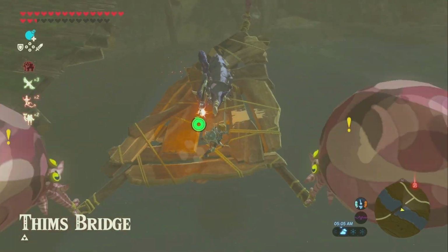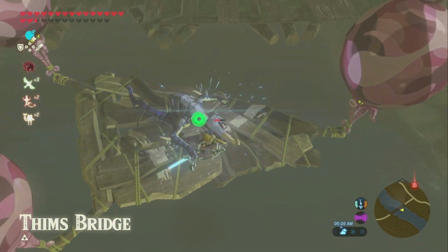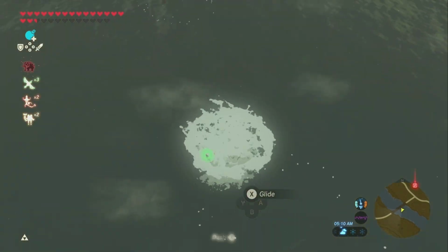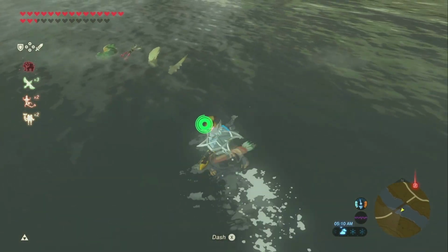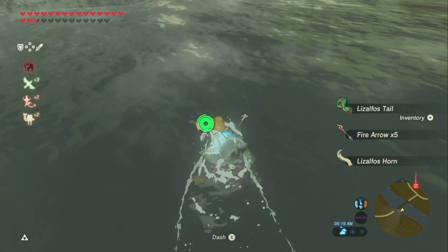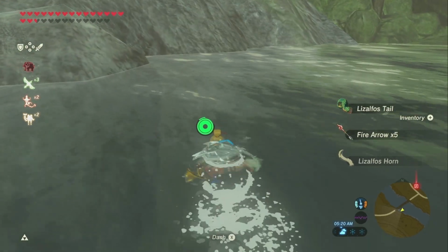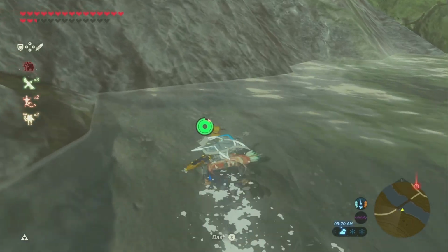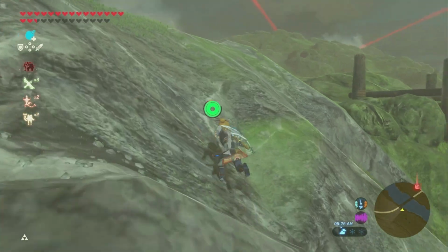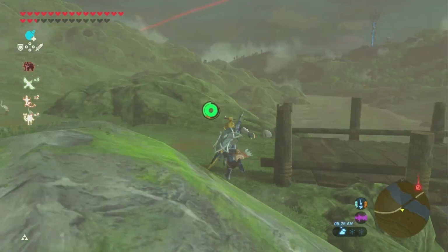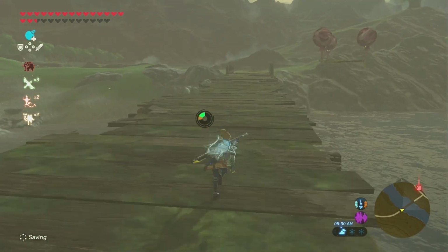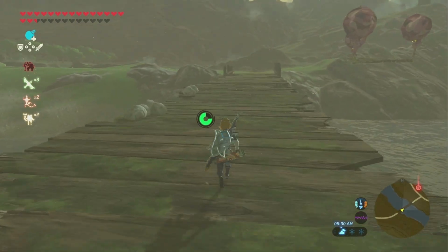Implications. There are safety implications where water heaters are in bedrooms, bathrooms, and closets. Fire and/or explosion are the implications where a water heater is not high enough off a garage floor. Damage to the water heater and possibly fire and explosion are issues if the water heater is not mechanically protected. Water damage to the living space is a possibility if there is no drip pan under a water heater above a living space.